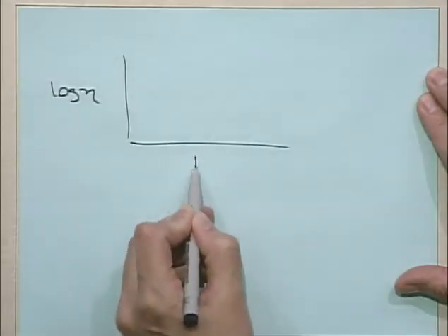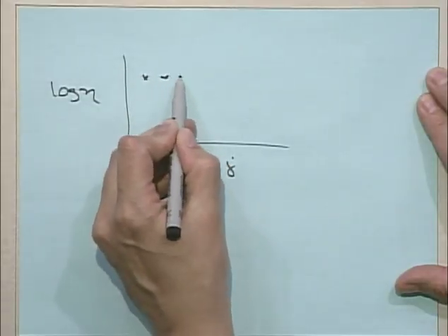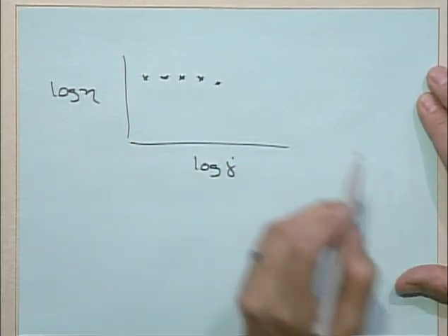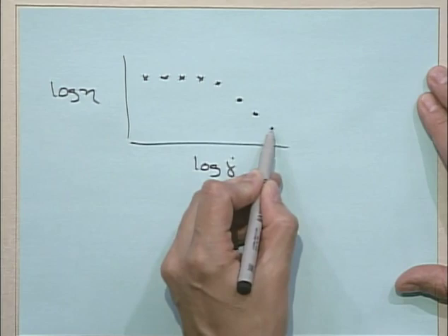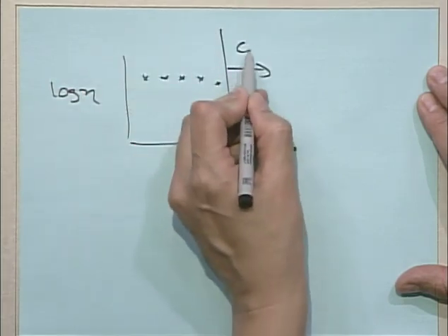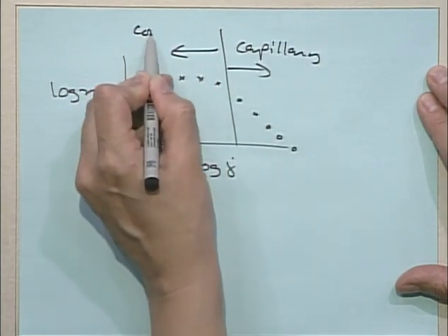So typically, when you see viscosity versus shear rate for a complete set of data, there'll be some data points, maybe including a little bit of shear thinning, and then some other data points at a very high shear rate. So typically, these data are capillary, and these data are cone and plate.